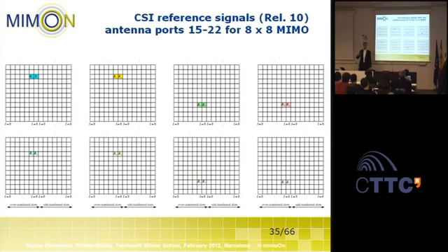The feedback to the transmitter is also facilitated in LTE-Advanced, and this feedback is also based on a codebook scheme. Similar to the pre-coding matrix, the user equipment selects a set of matrices from a codebook, and these matrices are fed back to the base station. Basically these matrices indicate the measured channel, this 8x8 MIMO channel.